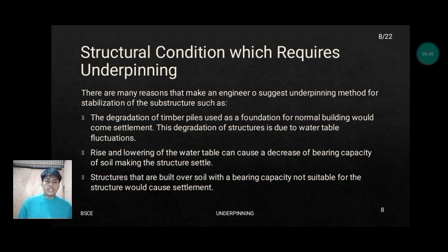This degradation is due to water table fluctuation. Rising and lowering of the water table can decrease the bearing capacity of the soil, making the structure settle. Lastly, structures built over soil whose bearing capacity is not suitable for the structure would cause settlement. These three are the reasons why we suggest an underpinning method for stabilization of a substructure.